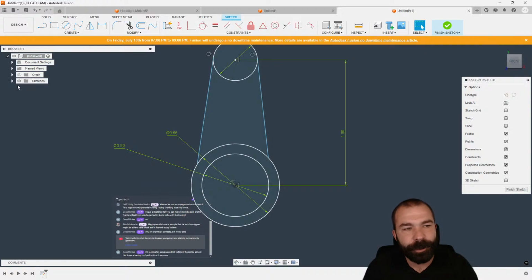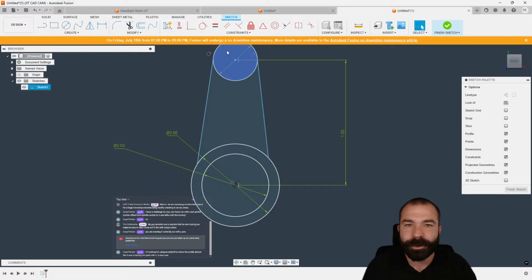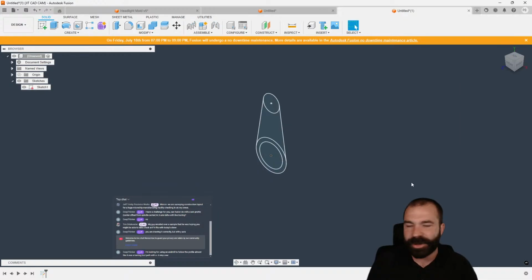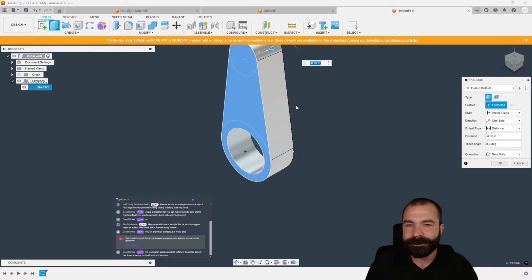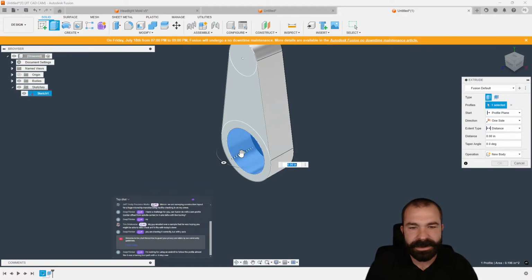It's also very important if you go to your sketch that you've created, you're going to notice I don't have that little red padlock. So again, tangent, tangent, tangent, and tangent. And now we got the little red padlock, which means we are fully constrained. So let's go ahead and get this profile strung out a little bit, and then do a second extrude on that sketch.